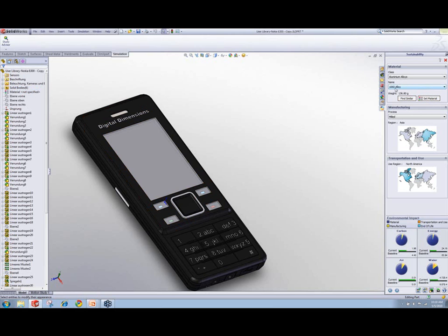So currently I've selected an aluminum alloy, a 1060 alloy. I want to choose which process I want to use to create the product, and I'll choose here from a good list of the different options we have available. I want to choose maybe the milled option. Most likely, if this is an Apple product, it's going to be created in Foxconn, so we'll select Asia for our area of manufacturing, and the transportation of it will majorly be inside the US, and the use of the product will be in the United States.